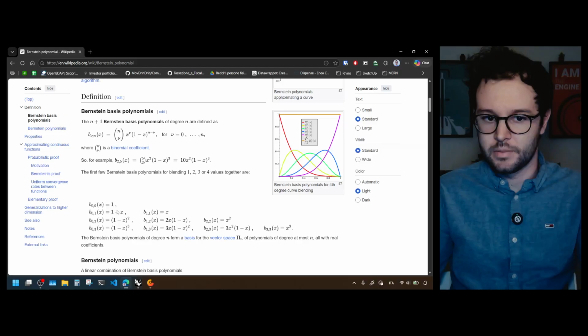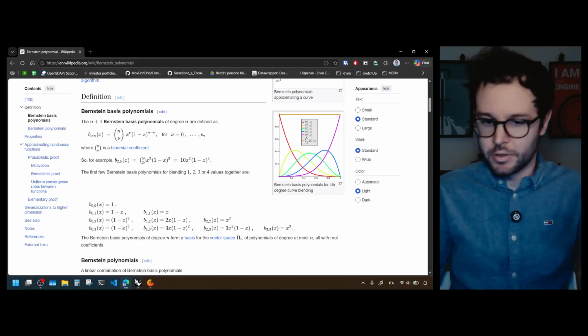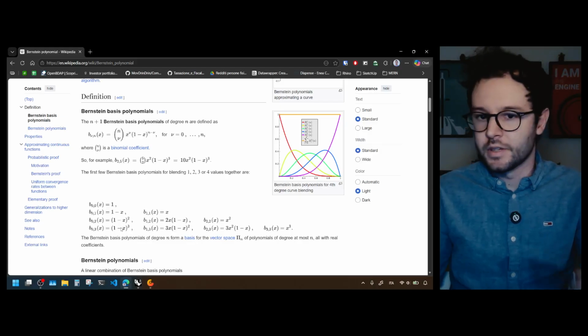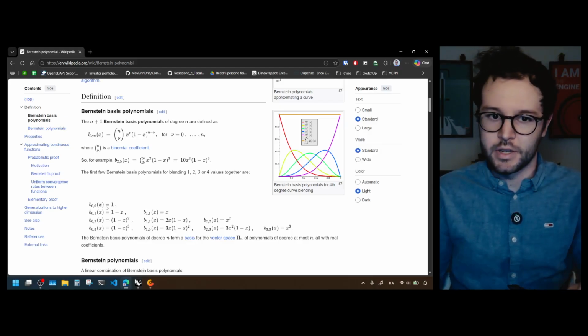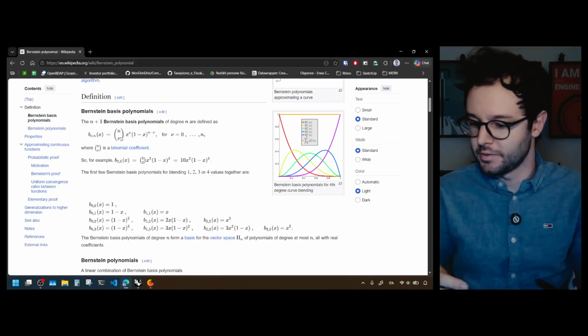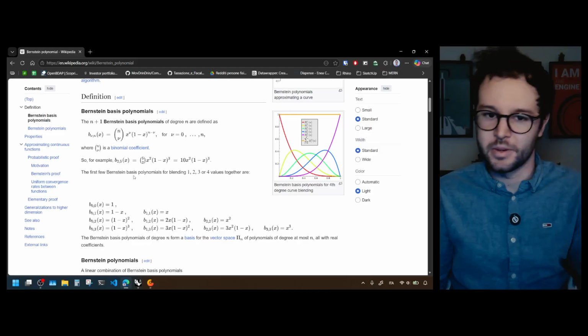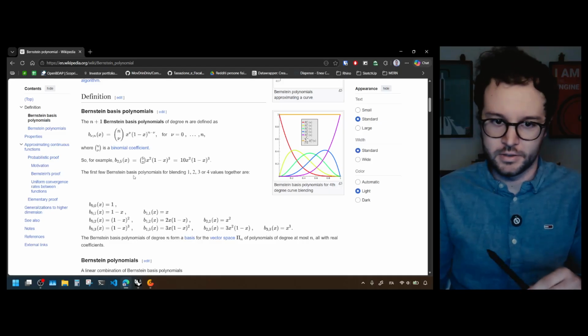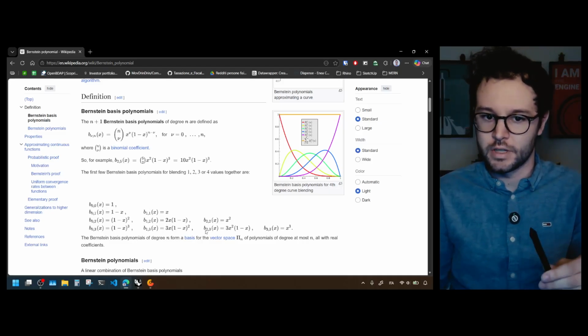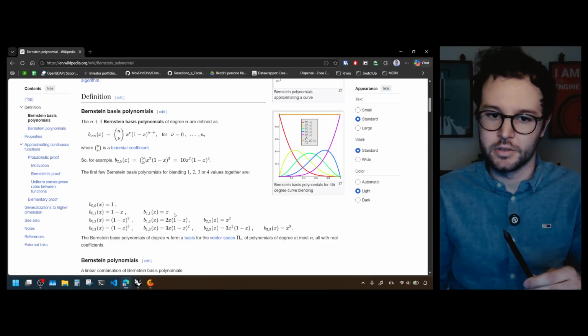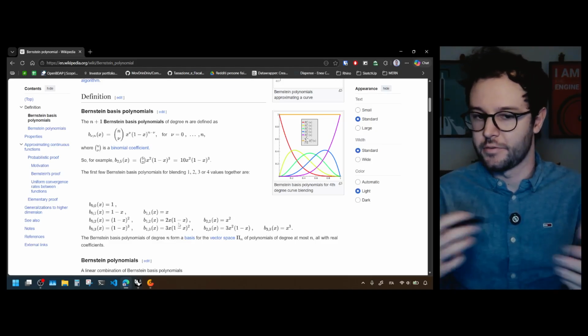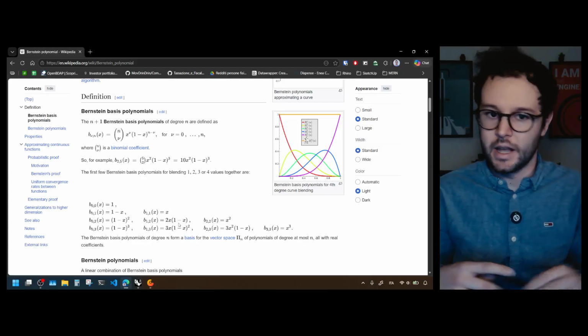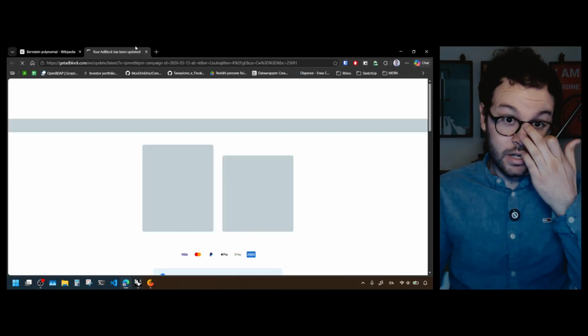This just shows the example for order 0, 1, which is just a line, to the parabola, 3 a cubic, which we'll see in Grasshopper shortly. You can go ahead as you wish using this binomial coefficient formula, which, if you click it, will show you what the binomial coefficient is. It's just using factorials to create coefficients. So these numbers here, the 2, the 3, are generated by that binomial coefficient, and then you have multiplication of 1 minus t elevated to a certain power multiple times.